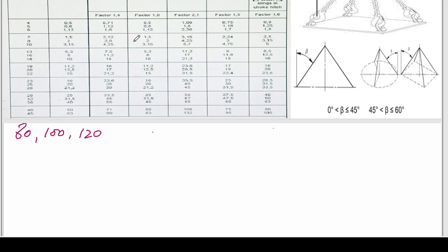Grade 80 is sometimes known as grade 8 or system 8, or it is marked as MA8 on the manufacturing tag. You will see grade 8, meaning MA8, written there. These chains have a high strength-to-weight ratio, making them suitable for heavy duty lifting as well as lowering applications. So these are the chains.